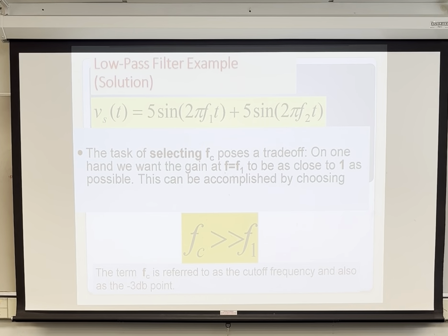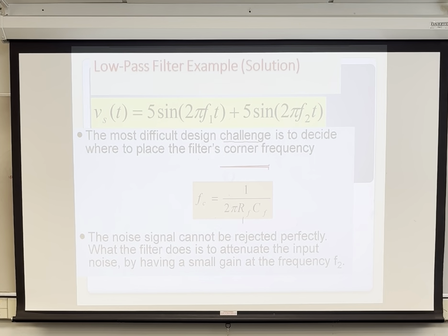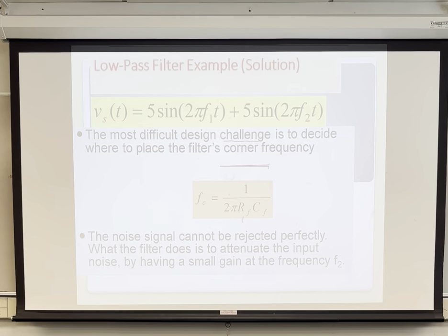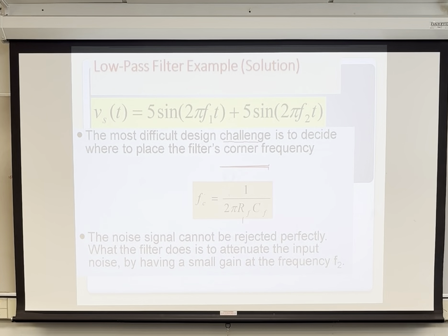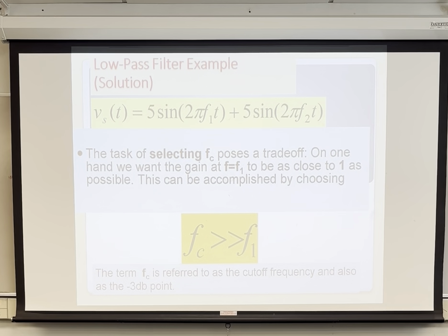The cutoff now is where we want the minus 3 dB point to be. So we're going to go back and change that slightly. Your cutoff is going to be above your calculated frequency, which is the Z number. F1 is going to be the last four digits of the Z number.